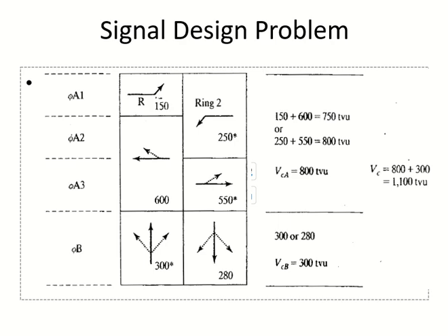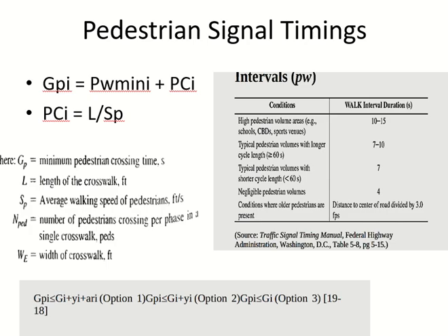What else will change? Yeah, change these times. Total time of the cycles will also change. Got it? So I will back calculate them. I will add them together, add the lost time together, I will get the new cycle time. Got it? Okay. So this is how you divide the green time.